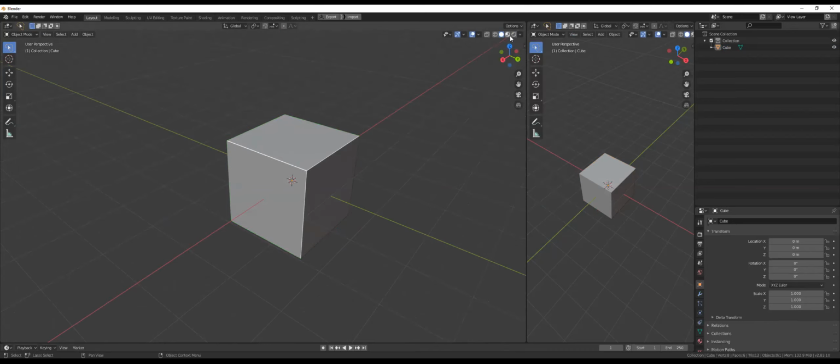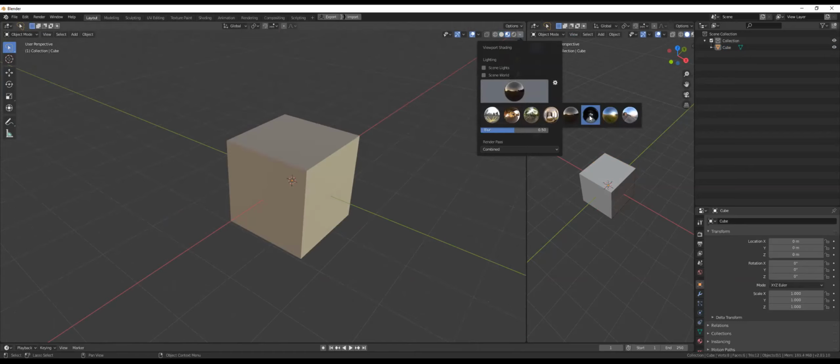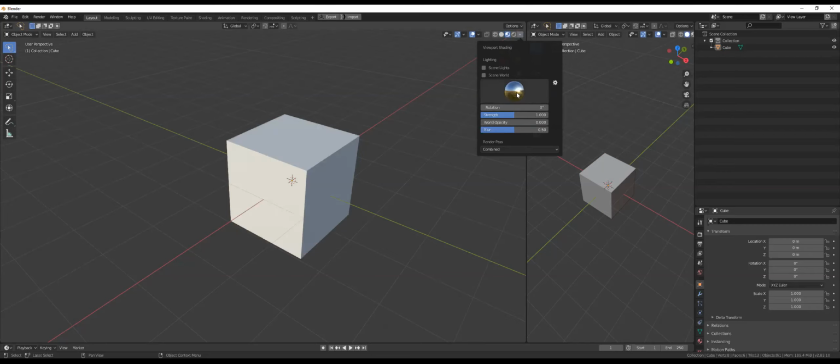Okay, here, if you change this HDRI shading, here are the settings of the HDRI. You can choose different types of HDRIs. I don't know how familiar you are with the HDRI concept. Basically, this is a fully panoramic view of a room or an environment or anything. And from that, the program is computing the lighting effects and the colors. As you see here, you can see a green and blue sky and the green grass and so on.